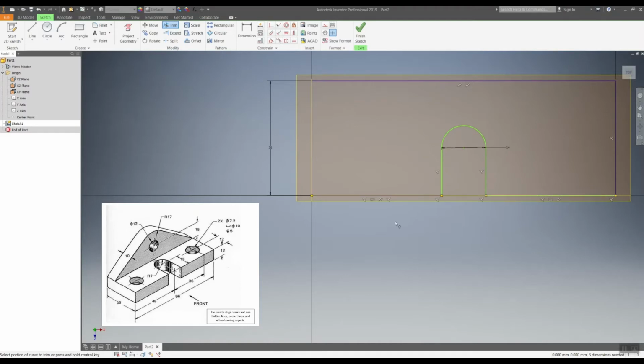But I think I want to put these circles in on this part. So I'm going to go over to my line here. If you look, 36 in each direction and 12 up will give me the center of my circle. So I'm just going to go over here. I'm going to go 36, and then I simply go up 12. What are the size of these circles? Well, these circles are 7.2.